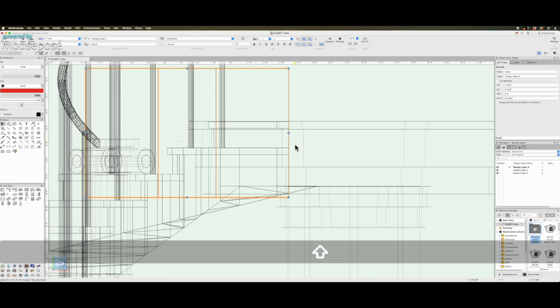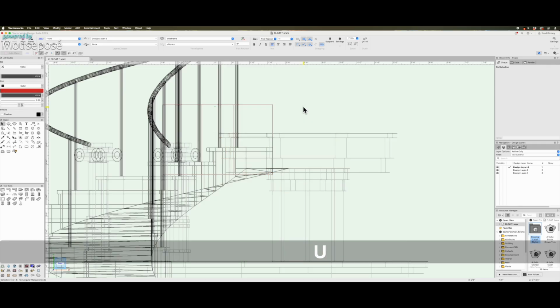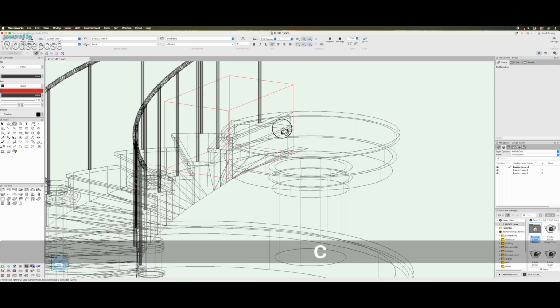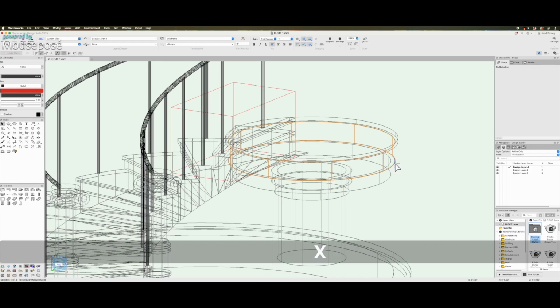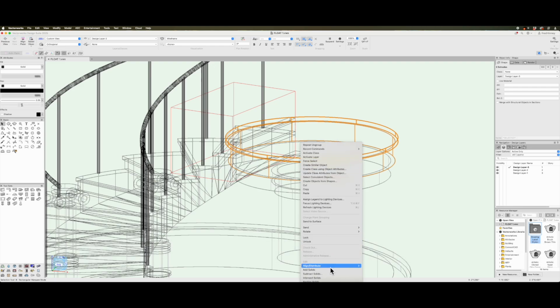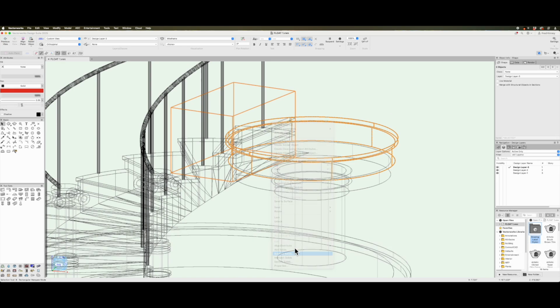And this is where you have a couple options. We could either combine this as one. Here, let's ungroup that for a second. Otherwise, we can't chop into it. We could combine this as one, then you can do it at one time, or you can do two edits. If we were to combine this as one, it would be like this. And remember, right click, add solids, and now click on this, and now subtract solids. We want to keep this part. We're going to hit OK.